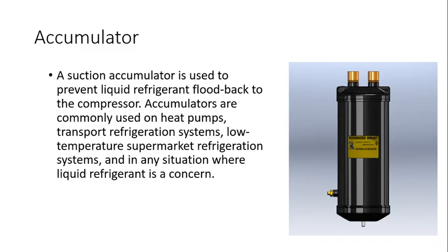Accumulator. An accumulator is an item that prevents liquid refrigerant from flooding back into the compressor. Normally used on a heat pump system. There are other applications for this, but in residential air conditioning and heating, it's going to be primarily in a heat pump.